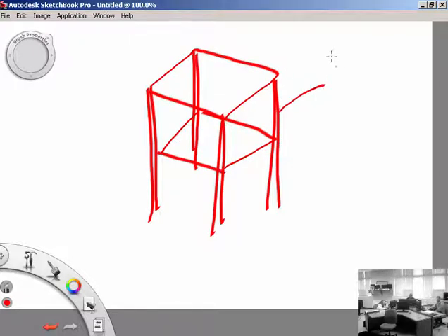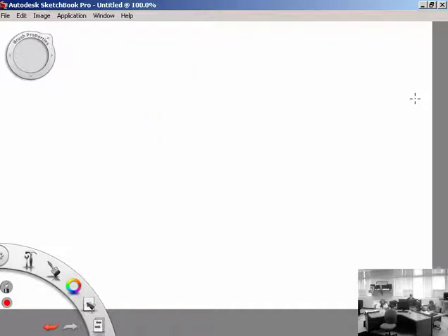So if my design calculations say I need a W12 by 72.4, is that likely to actually be something I can buy? No, it's not. I'm going to have to choose something that is in the range of what I'm after. So finding the materials and understanding the shapes is the big deal.